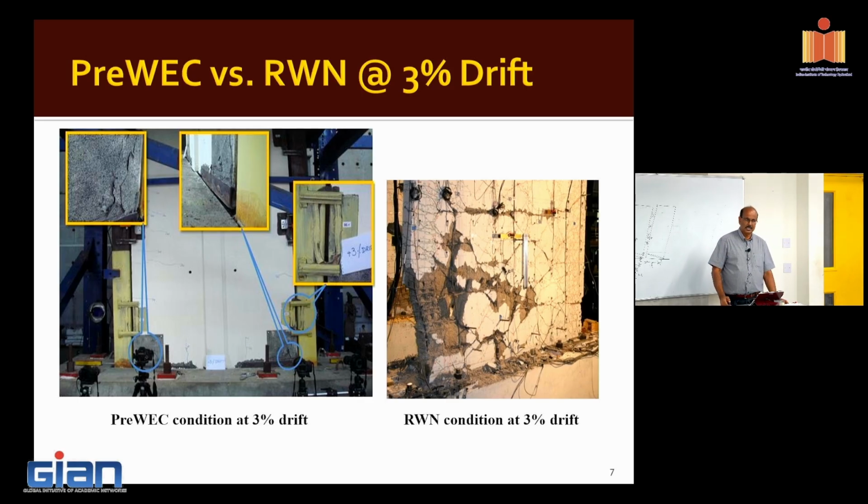Some committee members in ACI argued with us that because we are developing a large gap at the base, the question was, what's going to happen to the floor? Well, I said it should be the same as the cast-in-place, but cast-in-place is not a concern. But what we did was we actually measured at the first floor level how much upward movement we get. It turned out that upward movement here is actually smaller than this.